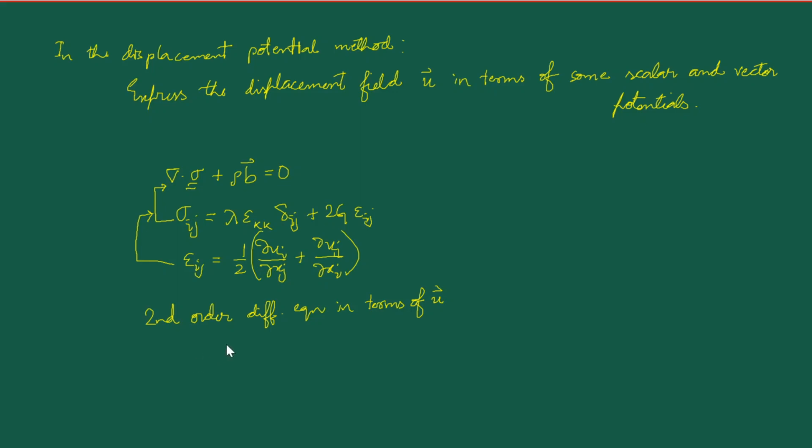Okay, so back when we were using the Airy stress function, we used directly the stress equilibrium equations, which was this, because this equation is directly satisfied by the Airy stress function representations, and we also went on to use the compatibility equations. Now we are going to use this equation represented in terms of the displacement, and the displacements in terms of the potentials. Please note that in this particular approach of this chapter, we are not going to need to separately take the compatibility equations.